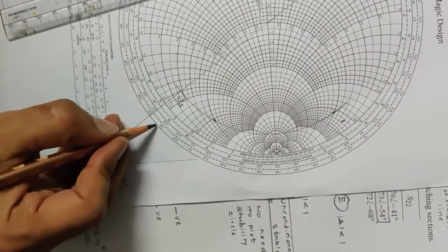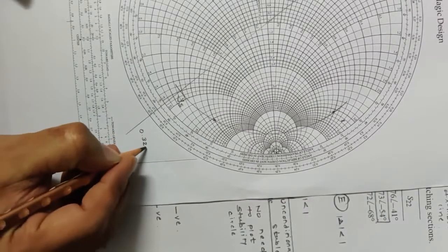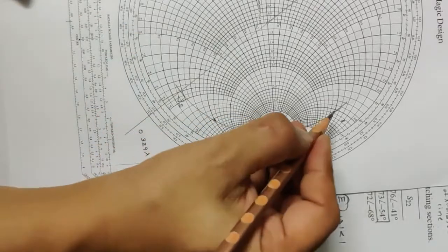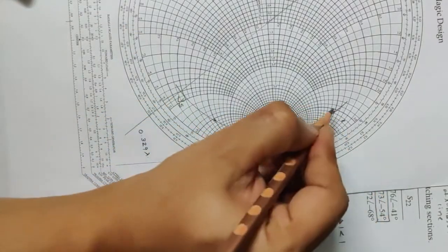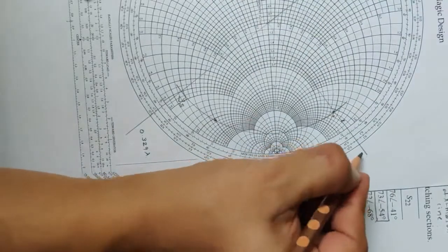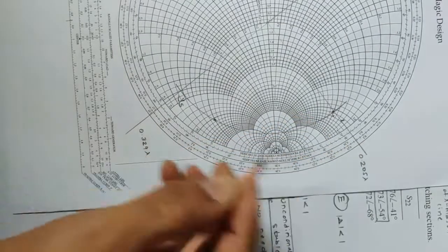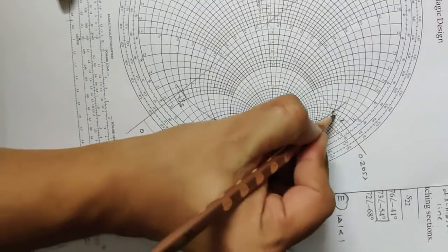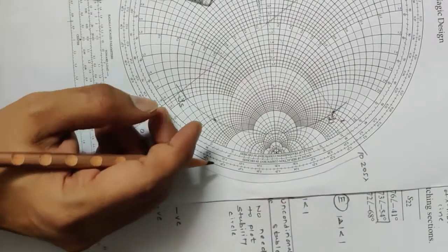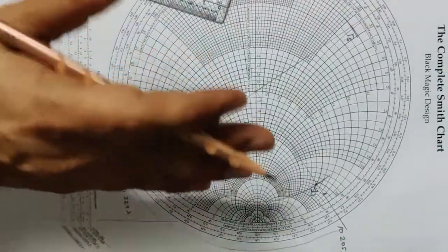So I will read this wavelength scale over here using outer wavelength scale. So it is around 0.329 lambda. You may get some different value, but near about this one you will get. Now this is the point of intersection of the constant VSWR circle and the unity circle. So extend this thing on the wavelength scale, and this turns out to be 0.20245. So one has to travel the distance from YS to Y1 over here in anti-clockwise manner, because we are moving towards load. Though this point is gamma S, we always move towards the load.